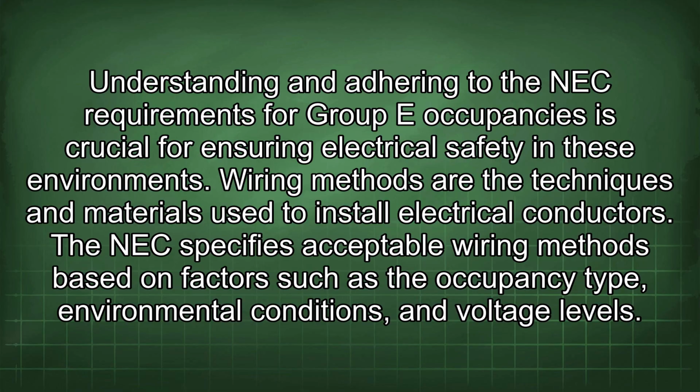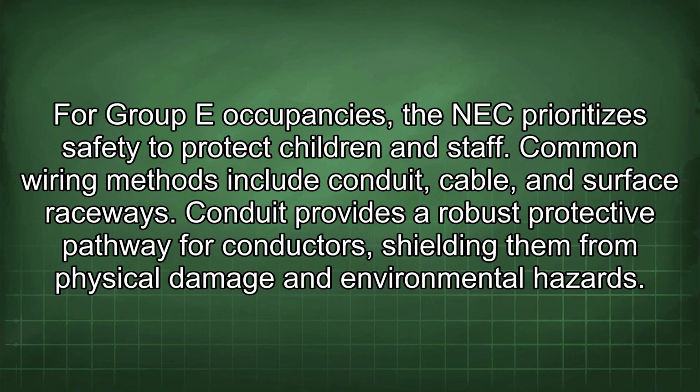Wiring methods are the techniques and materials used to install electrical conductors. The NEC specifies acceptable wiring methods based on factors such as the occupancy type, environmental conditions, and voltage levels. For Group E occupancies, the NEC prioritizes safety to protect children and staff. Common wiring methods include conduit, cable, and surface raceways.